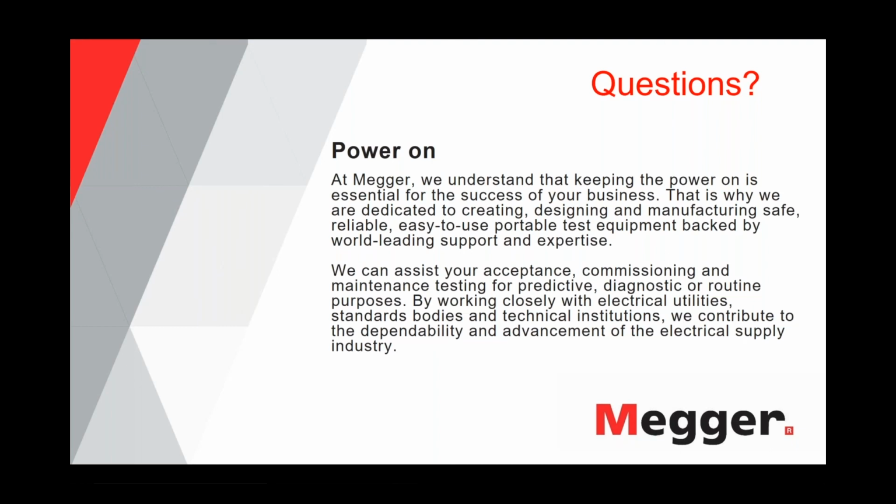First of all, we even offer this, so you can apply guard rings and do a tan delta measurement. However, what you need to have is at least 2 or 3 phases, because what you do is take the leakage current over the termination that you don't want to affect your tan delta reading, because it has nothing to do with the insulation condition.